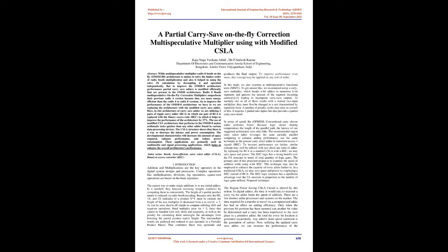But to improve the OMSB 8 architecture performance, the partial carry save adders present in the OMSB architecture are modified efficiently. Radix 8 Booth multispeculative on-the-fly correction multipliers outperform their previous Radix 4 version because the Radix 8 versions are more energy efficient than the Radix 4.